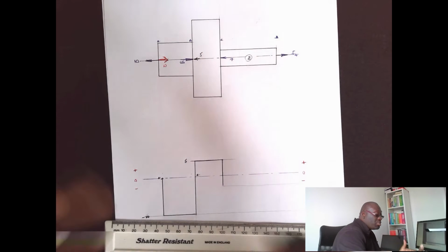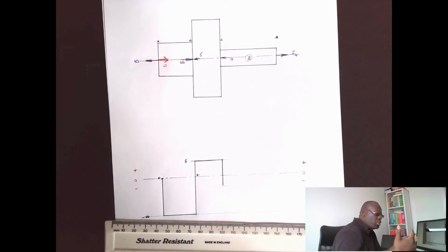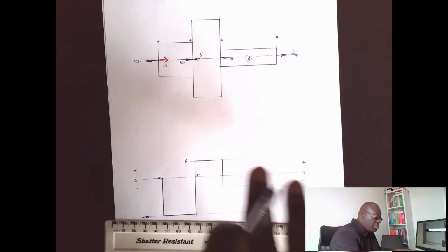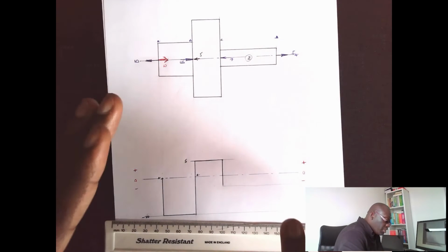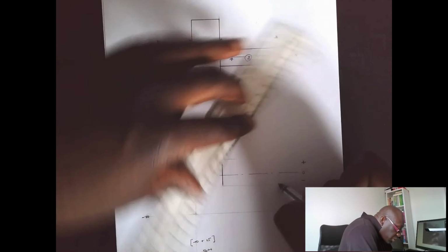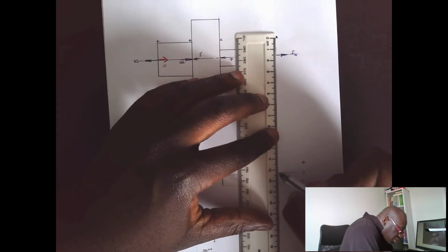So the external force to counter that compressive force from minus 2 needs to equate to 2. So we need to project from minus 2 back to the 0 line to ensure that the internal force system within the component is in equilibrium. Thus, we're going to project back to the 0 line.